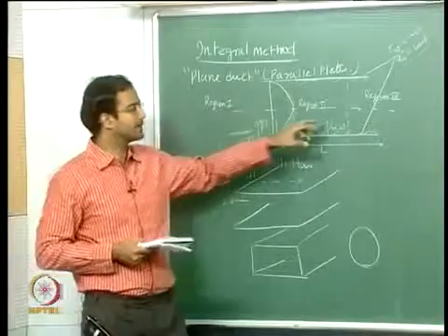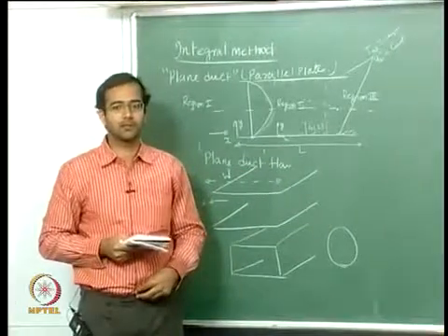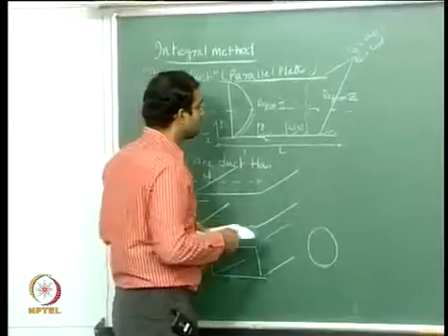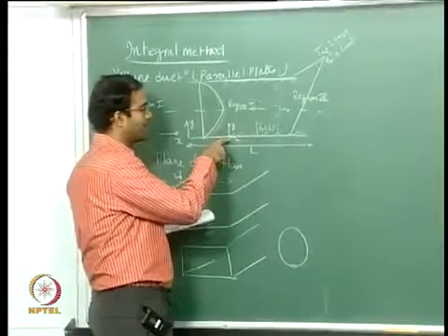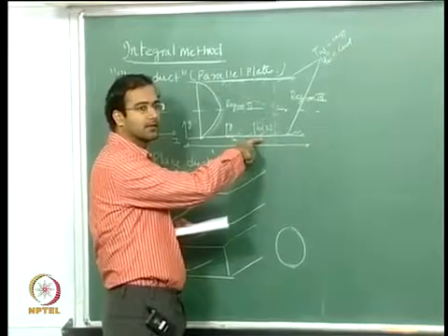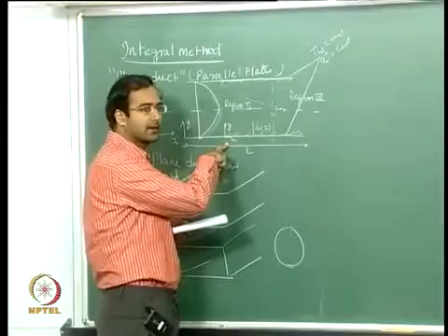Okay, so once the viscous effects start coming, then the definition of your actual boundary layer approximation will not be valid. Okay, so therefore you can see within region 2 it can be applied from the start of the boundary layer to a certain distance downstream.